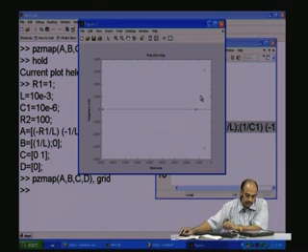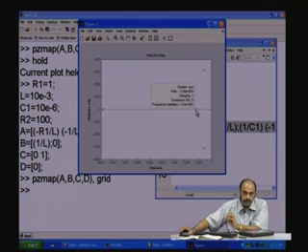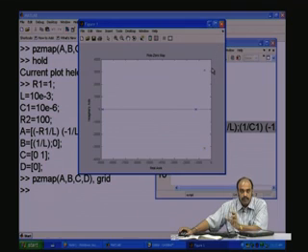So, you see the plot here. This was the earlier plot on the real axis, and now these two poles, the green ones, are the ones after having changed the parameter R2. So, as R2 starts going towards infinity, these two poles will become complex poles with a mirror. That is why the 180 degrees phase shift, and they gradually start moving towards the imaginary axis, which is this axis, and become more and more oscillatory.